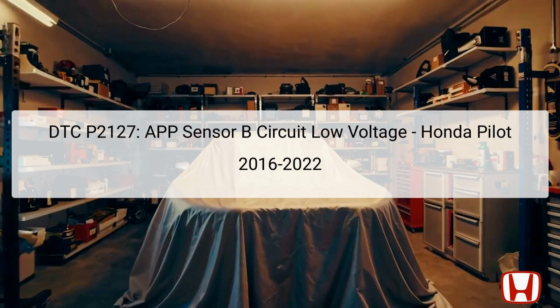This presentation covers the Diagnostic Trouble Code DTC P2127, which indicates a low voltage problem in the APP (Accelerator Pedal Position) Sensor B circuit, specifically known as TP (Throttle Position) Sensor E. This issue affects the vehicle's ability to accurately measure the accelerator pedal position, directly impacting engine performance and throttle response. The DTC is confirmed when the failure is consistent and reflects on the Powertrain Control Module (PCM) data.